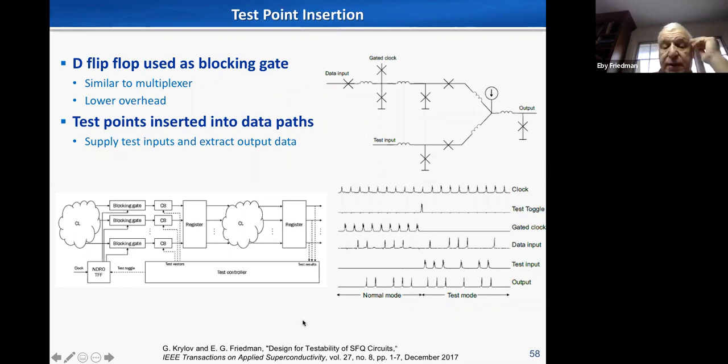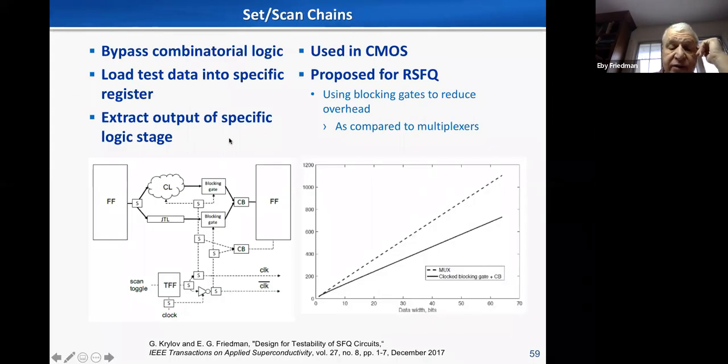This is a relatively older paper, a few years ago, 5 years ago, but we've developed ways to control and manage the distribution of the test point and allow us to improve our testability, both control and observing. We're looking at different structures, bypass devices, and again, we basically use the standard CMOS ideas and transpose them into RSFQ. I've got a student now actually working on expanding this into a much more SFQ specific family of DFT techniques, which are important.